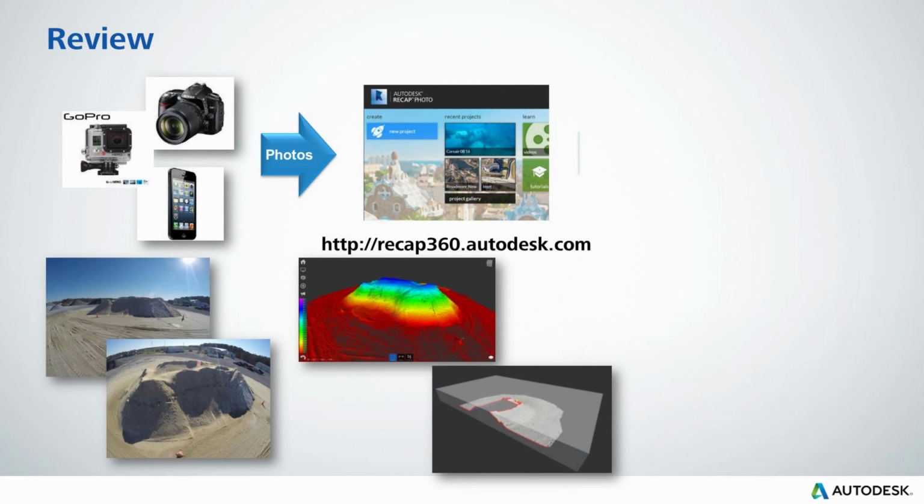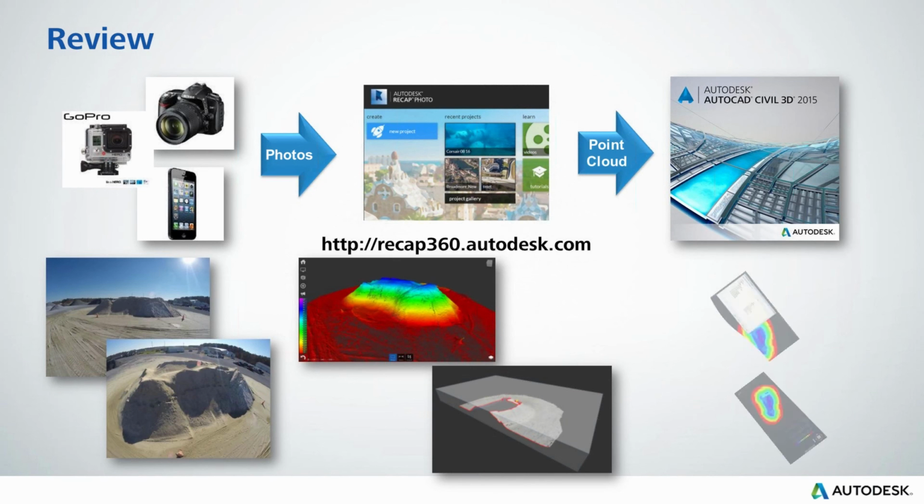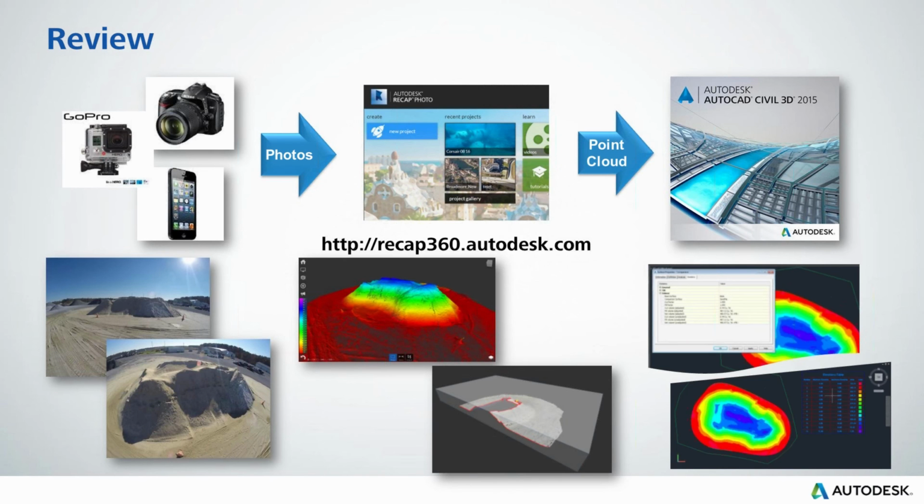And that point cloud can be brought into ReCap and cleaned up and analyzed as you see fit. And we're going to bring that data back into Civil3D for volume comparison. Maybe we need to create volume tables. And we can track all of that data inside of Civil3D for the life cycle of the stockpile. So I can then compare the volumes created or the surface created this month to the volume or surface created next month and get my difference as well.